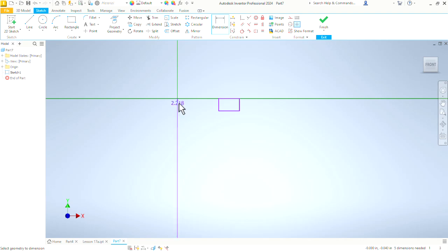Let's put the inside diameter, hit that edge. Let's make that 0.750. Then we will define the width of this wire. Make that 125. I could also do 1/8, eighth of an inch, 125. Let's make this height, let's say that was 3/32, which is 94 thousandths.